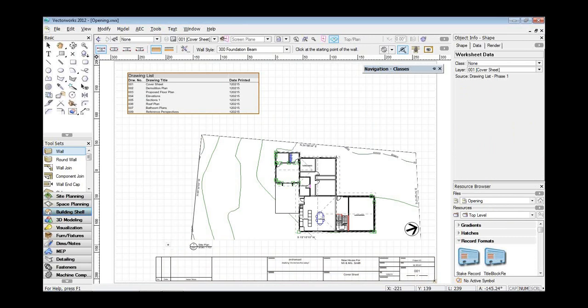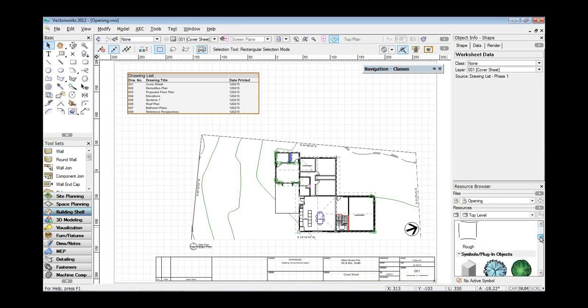Okay, so are you happy with that answer, Vin? No, yeah, sorry, I just got sidetracked there. Here's the follow-up on the wall specs after creation question. He said, for instance, can you change a wall from solid to a sandwich construction? Yes, I thought that's maybe what you meant. What you're actually talking about is editing the wall style.